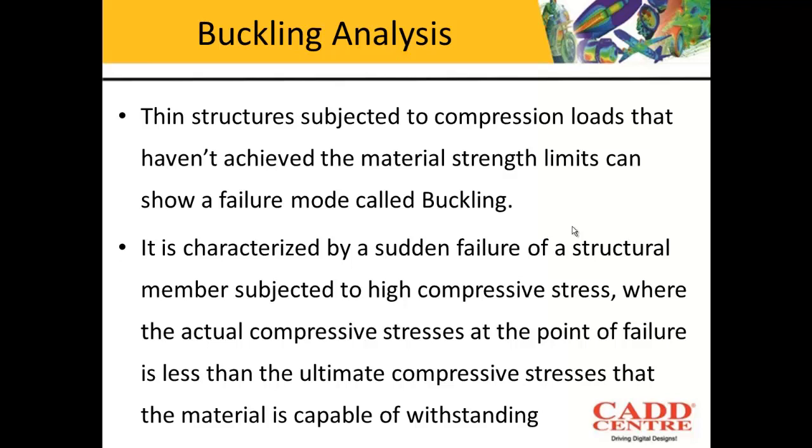Now buckling is a sudden failure of a structure when it is subjected to high compressive stresses, where the actual compressive stress at the point of failure is less than the ultimate compressive stress. Whenever we apply compressive loads on a long slender object, some stresses will be generated.